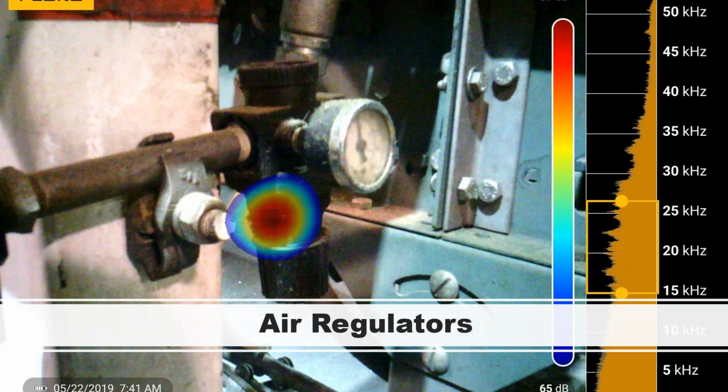Same kind of things here. You find these regulators having problems on a regular basis too, because they're subject to a lot of vibration. People don't think that that's a consumable part that needs to be swapped out every now and then, but we find leaks on the O-rings and the seals of these things all the time. We find leaks on the back of the gauges, any number of things. Anywhere there's a potential connection there, you can have some kind of failure. These regulators are notoriously bad.